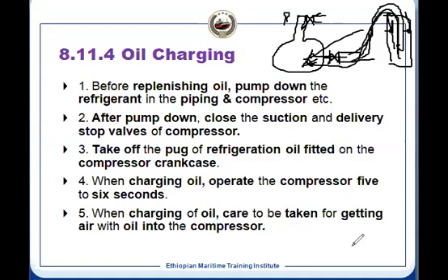So this is one of the ways we can charge the crankcase. We can replenish the crankcase oil. If there is a leakage and the crankcase oil level has gone down, we can fill it up by this. It depends on the side glass, by which you can see the oil level, how much oil you want. Once oil is going inside, the pressure is increased. At one point, it will be the same pressure, and nothing will move from this direction.